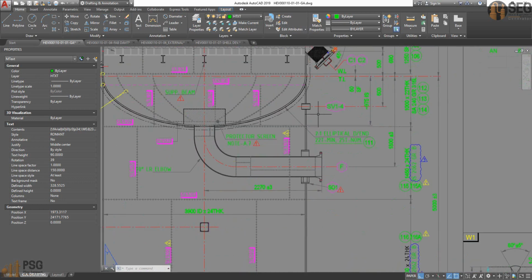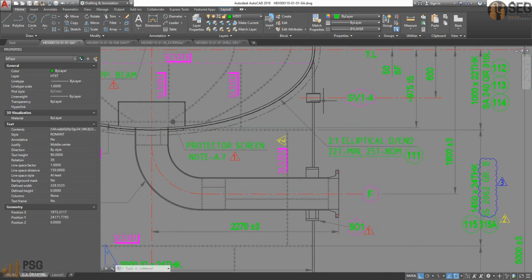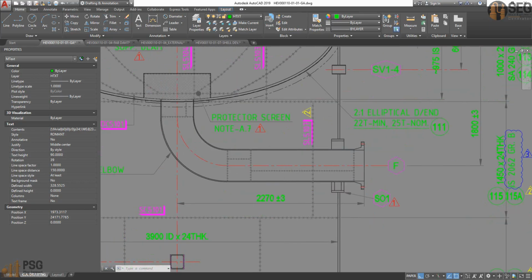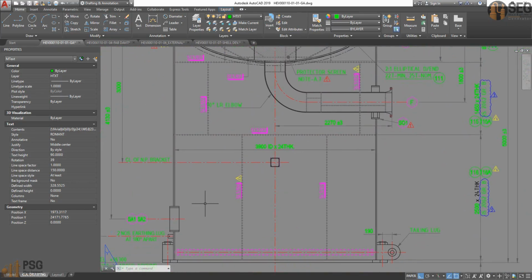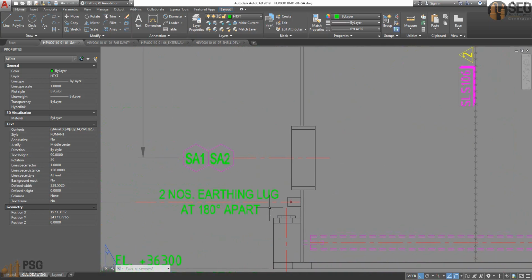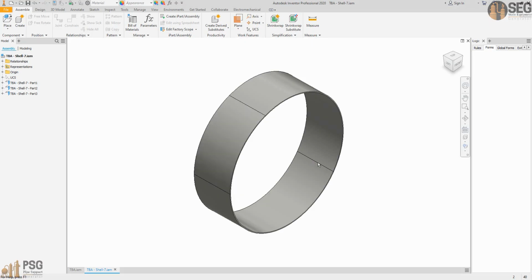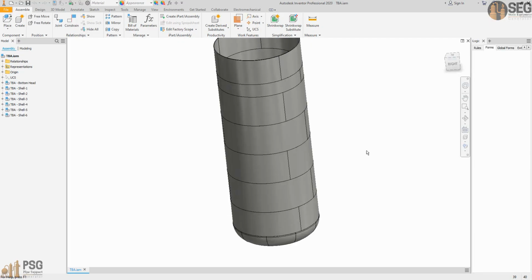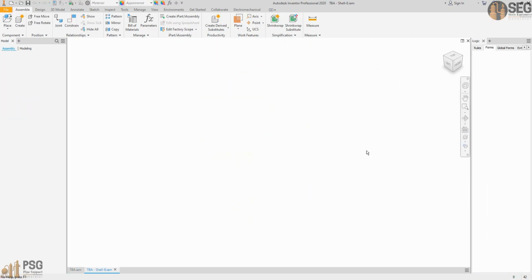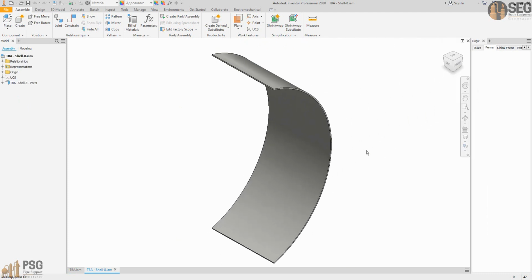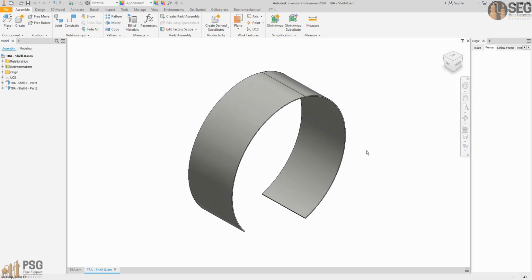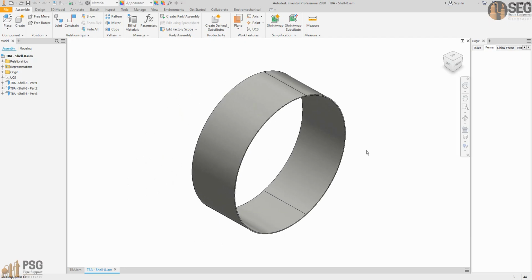So we will learn in the second part of this video how to add those nozzles on the bottom head and how to make the saddle nozzle vents or skirt vents, nozzle opening and skirt access, and how to add an external item like the earthing plug. But in the first part we will discuss how to generate the main items and the support skirt. Now the can number 7, we have one more can, which is can number 8, which is shell 8. After that the top head will be generated.